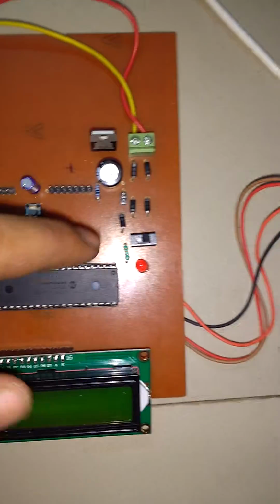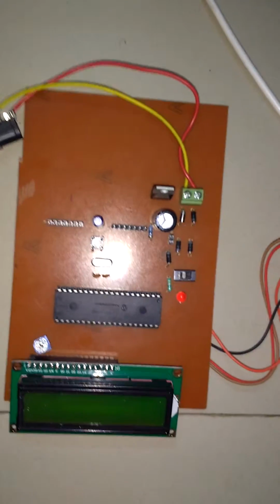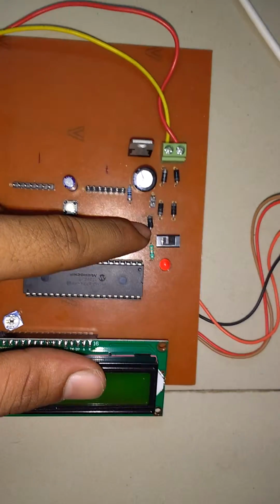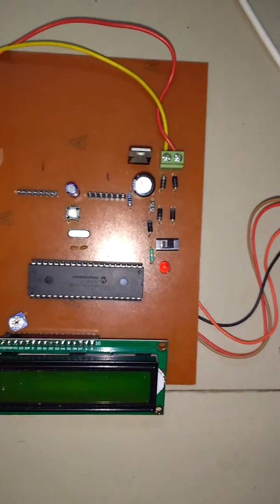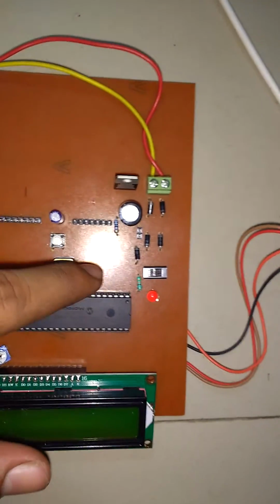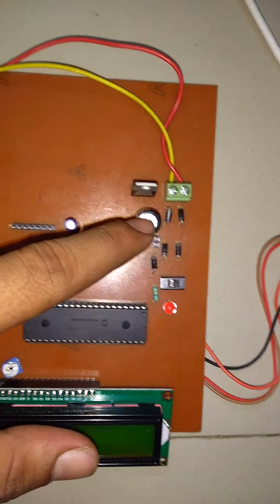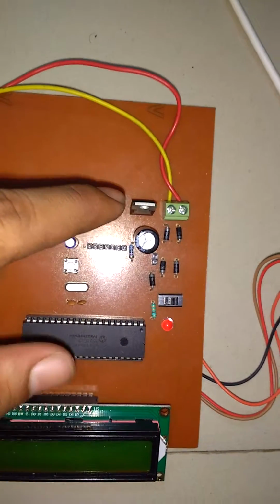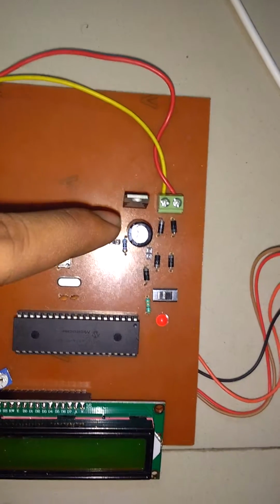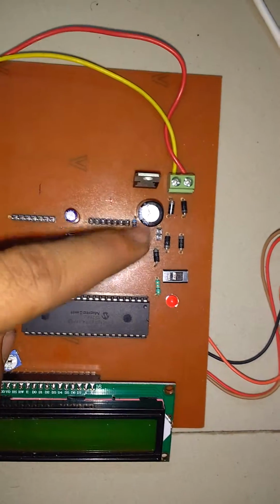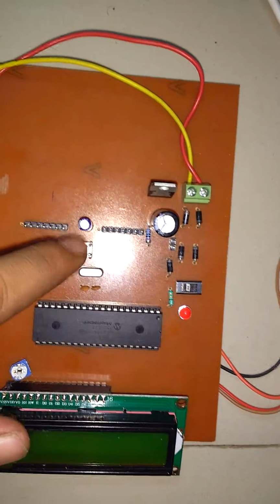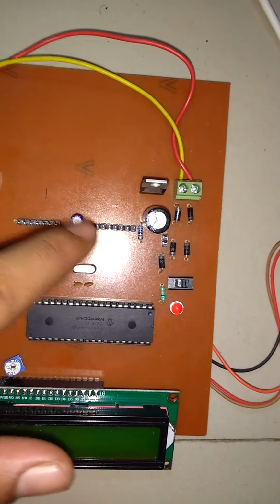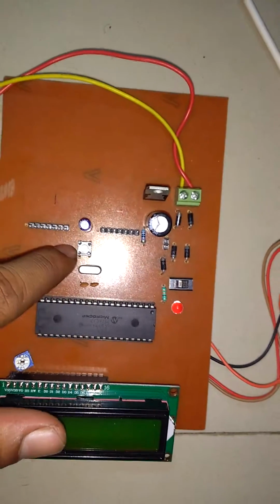There might be a chance that some short circuit will happen in the circuit, and due to that the whole power supply circuitry will burn out. To avoid that, we used one diode, which will protect against reverse current. Here one capacitor is present. The capacitor is used as a filter, and a 7805 is present to get a fixed regulated 5 volt supply. Besides the capacitor, one resistor, one capacitor and a switch are present. This resistor, capacitor and switch form a reset circuit.